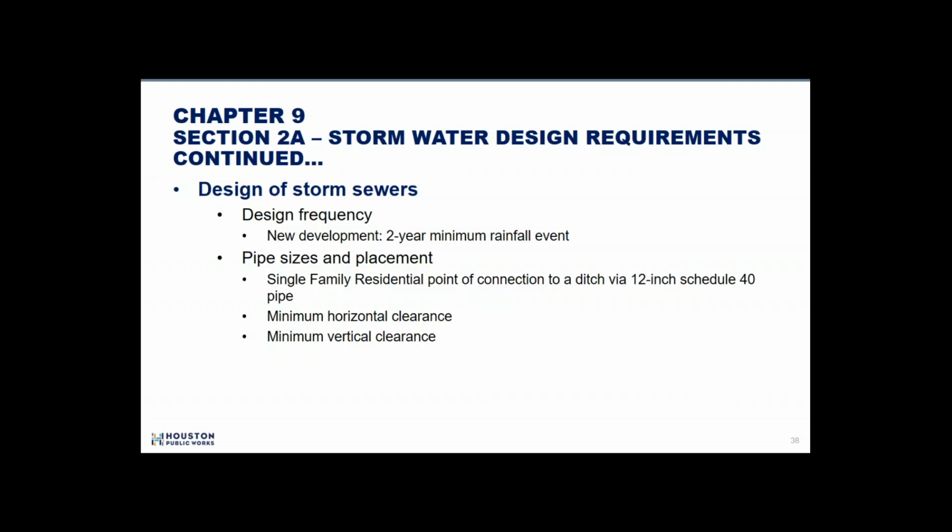And then the minimum vertical clearance, that's had an awful lot of discussion over the last few years, because a previous city engineer did write a memo. It was unsigned, that basically allowed for something less than 1.5 feet. Transportation Drainage Operations wants to maintain, for criteria's sake, 1.5 feet clearance in all cases, no matter what construction method is used.